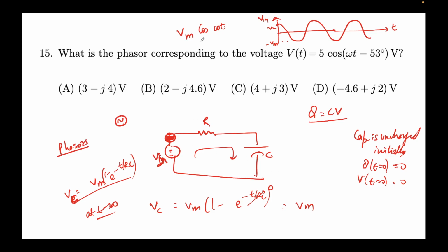If the input voltage is itself oscillating, then the voltage that will appear across the capacitor will also have a sinusoidal component, right? It will have the DC value, which stabilizes at whatever the value is, but it also has a sinusoidal component, or the AC component, which we may call it. And this is referred to as the sinusoidal steady state.